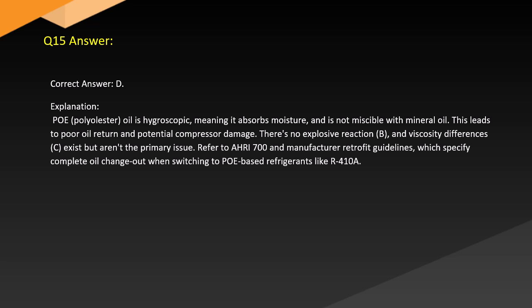There's no explosive reaction (B), and the viscosity differences (C) exist but aren't the primary issue. Refer to RSES and manufacturer retrofit guidelines, which specify complete oil change-out when switching to a POE-based refrigerant like R-410A.